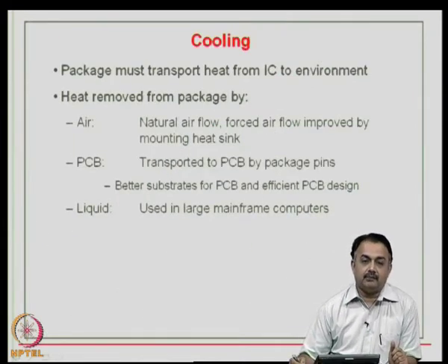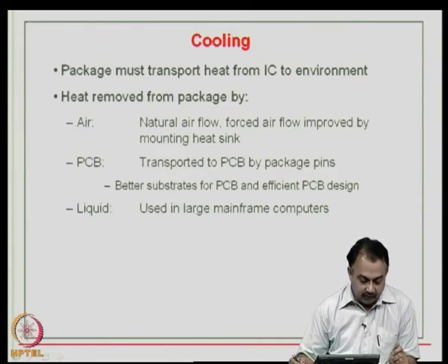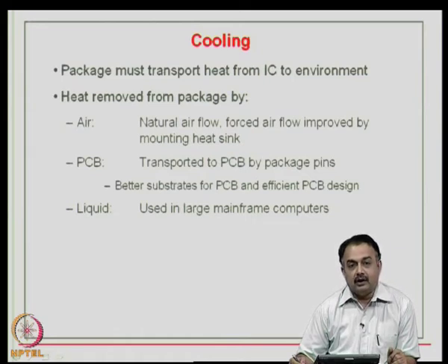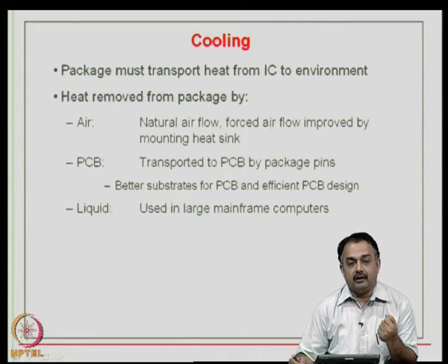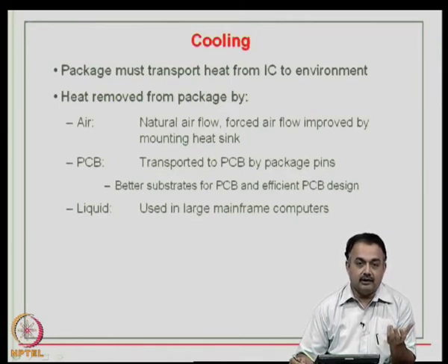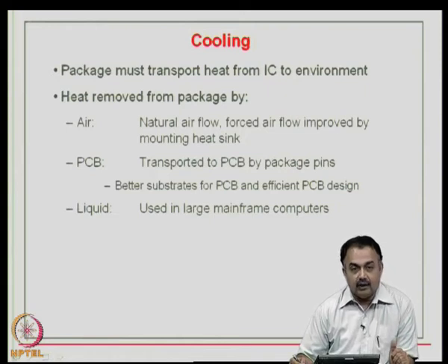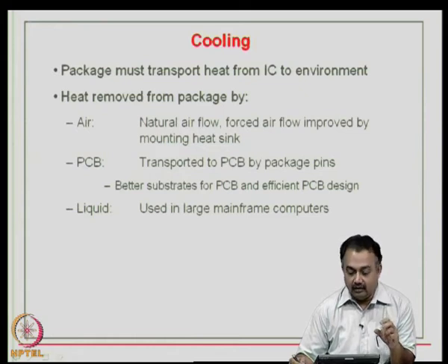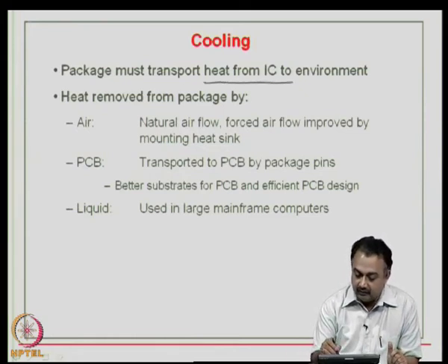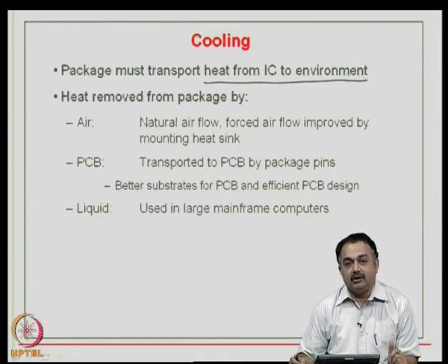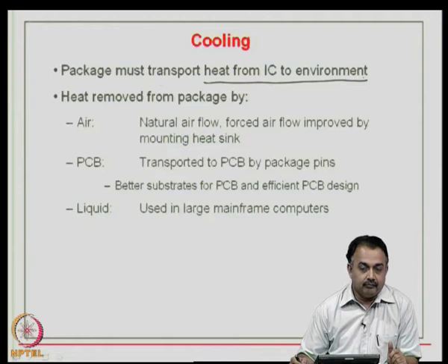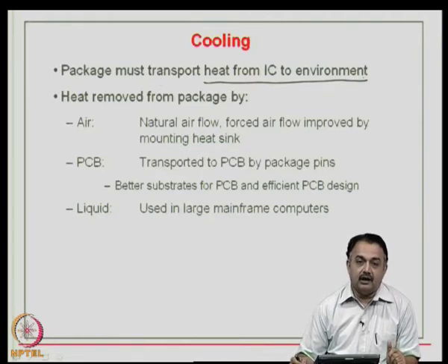Another important aspect when you look at packages would be the cooling phenomenon. So, when a die is packaged and connected to the external world by means of a lead frame structure or a solder ball arrangement in an area array format, whatever be the case, the package must transport heat from the core die to the environment. So, heat from the IC to the environment should be faster, quicker, and effectively removed.